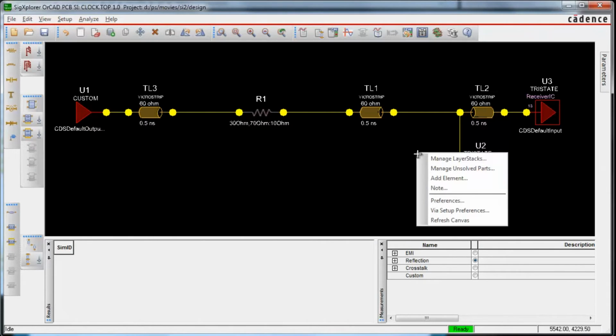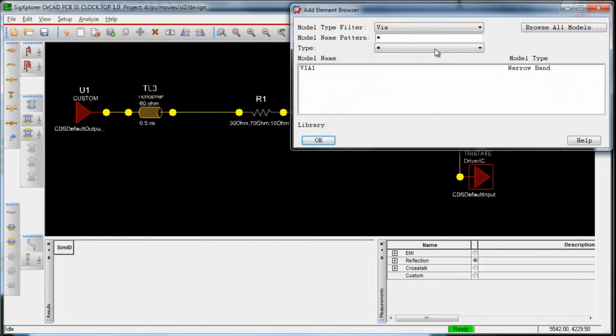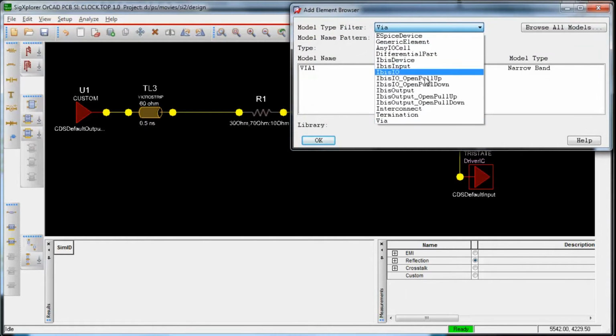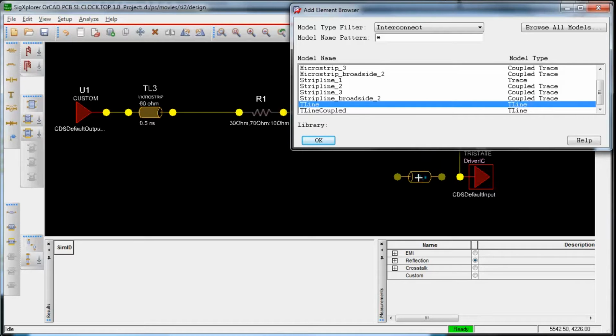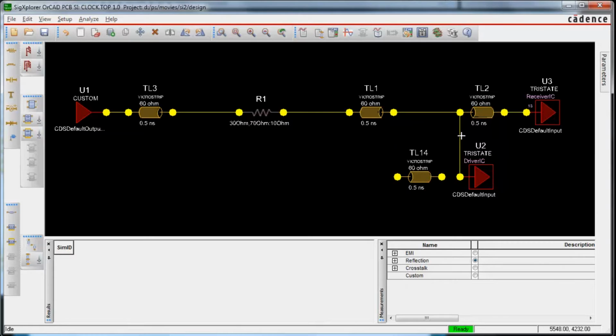Net topology elements such as vias and stripline or microstrip transmission lines can be modified or added to achieve performance or characteristics. Connectivity of the topology can also be edited to include new components. A T is automatically inserted when more than two transmission lines are connected to each other. For what-if analysis, a range of values may be specified for one or more components. In this case, the resistor value is swept from 30 ohms to 70 ohms in steps of 10 ohms.